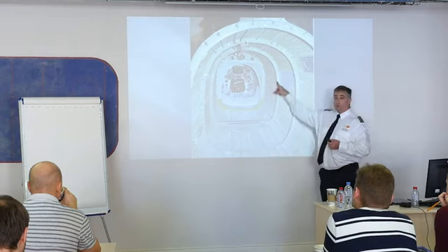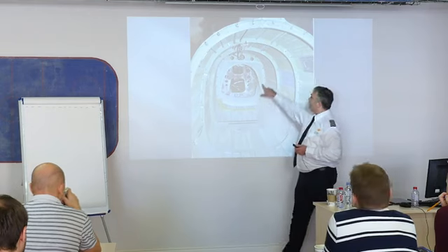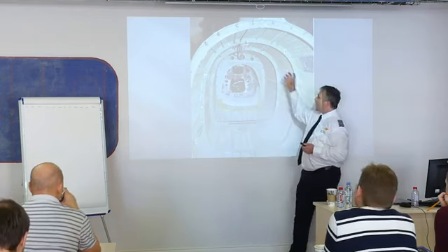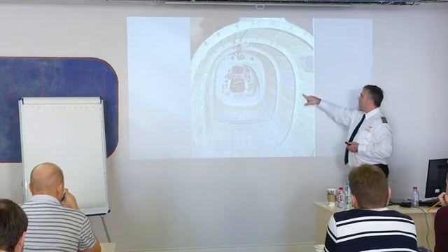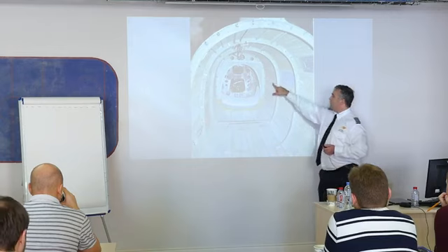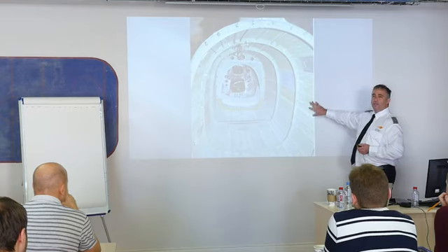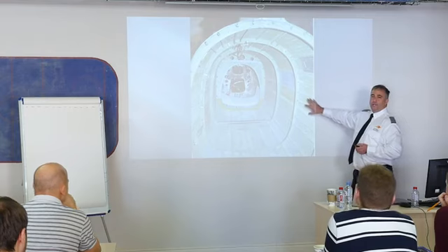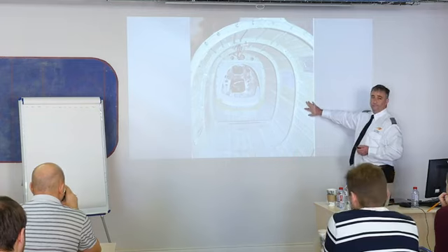Attaching each one of these formers, and you can see here I have an actual bulkhead, or something that forms with rigidity, right? Attaching each one of these are longerons. That's what this one is called right here. And stringers. Now, each one of these increases the rigidity of that fuselage, increases the rigidity of that airplane.